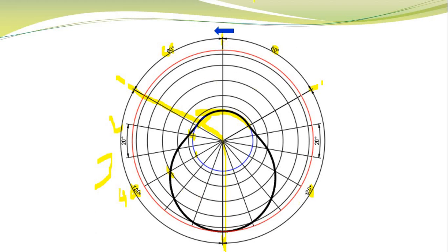When you're doing this cam profile, the thing that you need to keep in mind is that you need to indicate the direction in which you're drawing your cam profile. So your cam was rotating clockwise, so your cam profile will be drawn in the counterclockwise direction. Keep that in mind and then indicate this direction. You don't need to put the 60 degrees and so on. I'm just doing that so you understand how I've got my cam profile in.